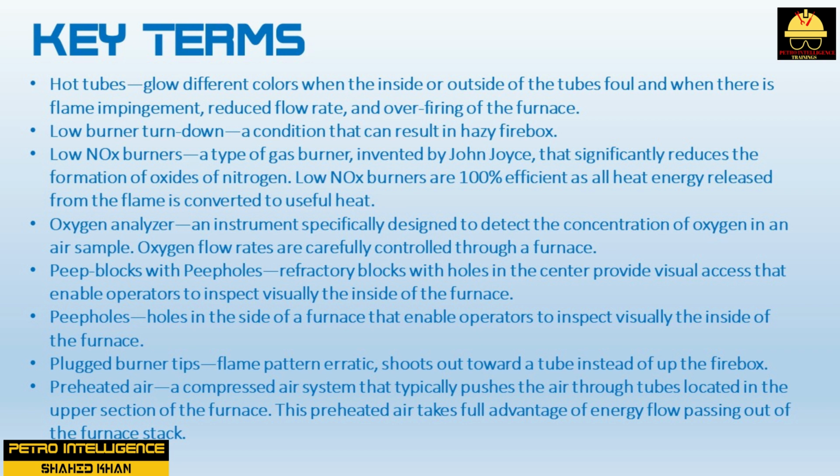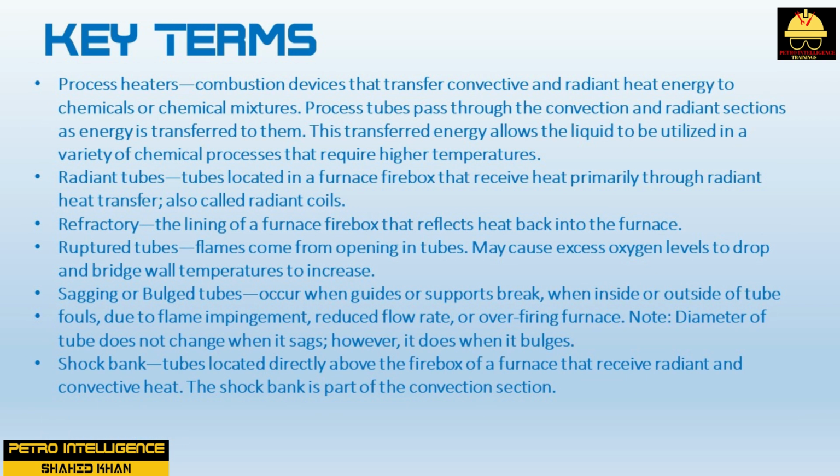Plugged burner tips cause the flame pattern to be erratic, shooting out toward a tube instead of up the firebox. Preheated air is a compressed air system that typically pushes the air through tubes located in the upper section of the furnace. This preheated air takes full advantage of energy flow passing out of the furnace stack.